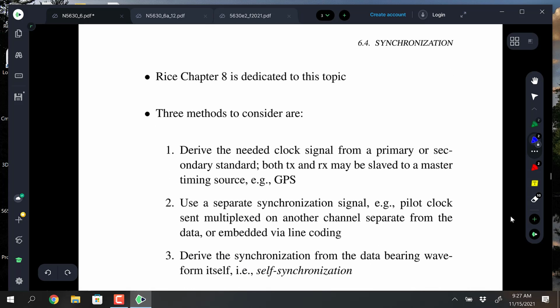Symbol sync also has another thing that you have to remember, which is that maybe the crystal oscillators between the transmitter and the receiver are very stable, and I'm now thinking including mobile communication. Doppler affects all oscillators, right? The Doppler effect doesn't just go after the carrier, it goes after the clock and oscillators too, but the carrier frequencies are so high that they see the Doppler shift very quickly, whereas the symbol clock doesn't see very much shift, but it still has a drift to it that's imparted by motion.